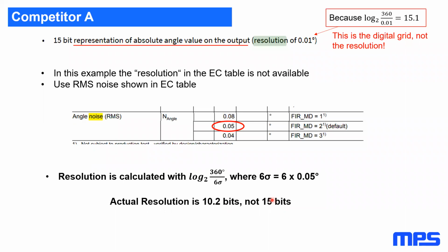So I think some companies either purposely or inadvertently take advantage of the fact that when you're comparing sensors, you just say, well, I need a 15-bit sensor. Oh, it says 15 bits. Cool. 15-bit sensor. You want to make sure that you take the time to find the noise. Sometimes you have to convert it into angle. As here, they did angle noise, but not always.